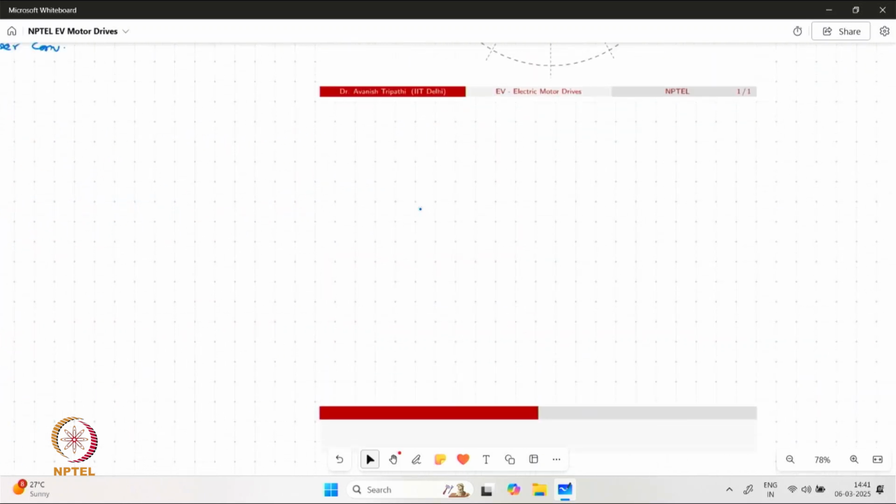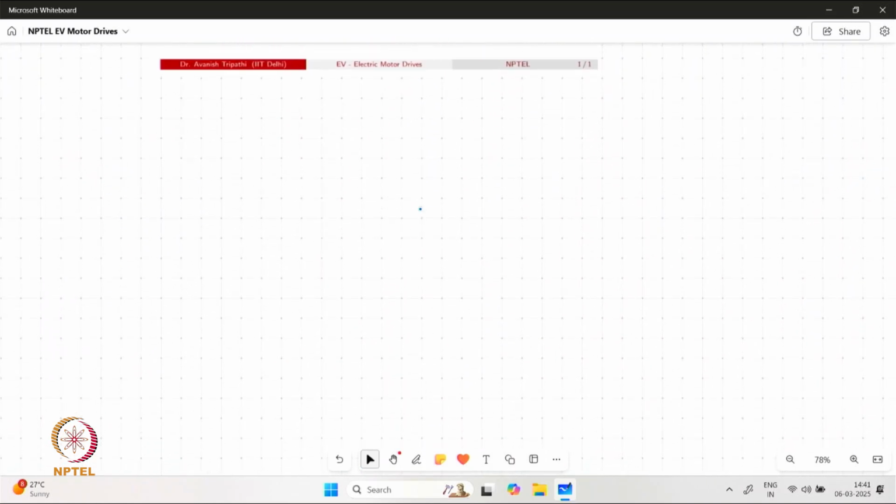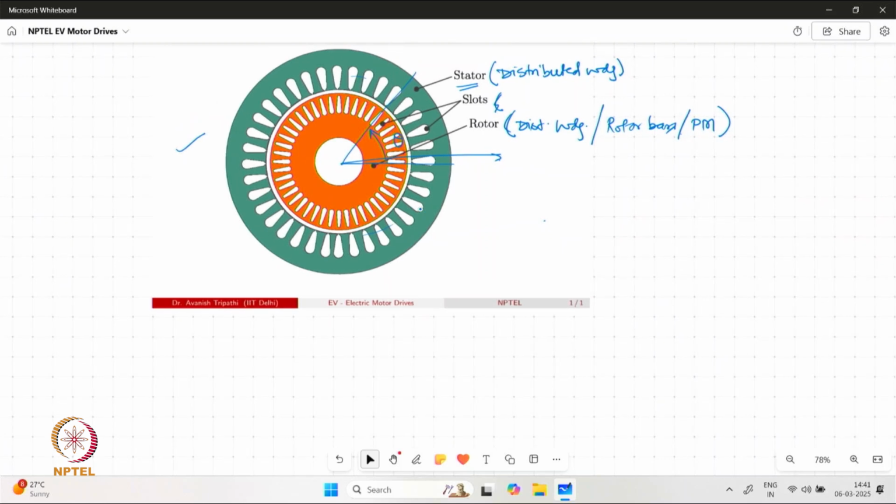Now, going ahead, if we want to draw the equivalent circuit for this machine, we again need to refer to one of the previous lectures where we saw this machine as a transformer. The windings on the stator and rotor side are isolated and we are providing supply possibly from one side or in general from both the sides.